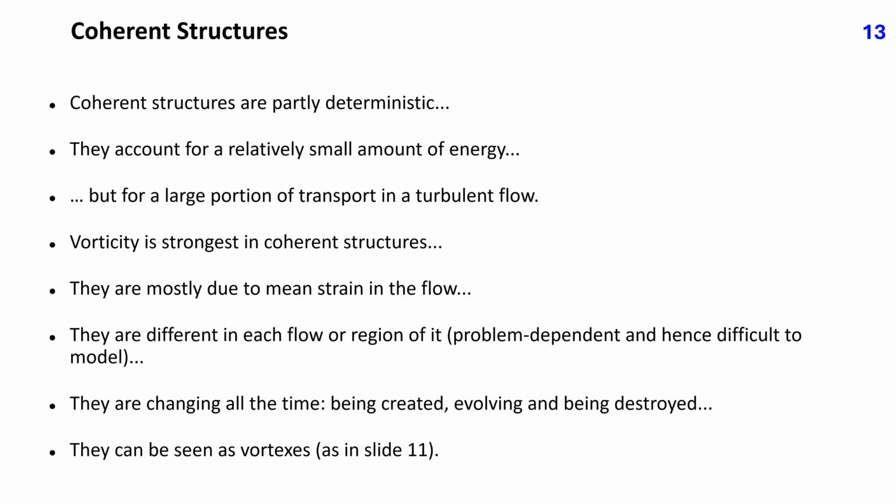Coherent structures are partly deterministic. They account for a relatively small amount of energy in the flow, but they are usually responsible for a large portion of transport in turbulent flow. Coherent structures are characterized by strong vorticity. They are mostly due to mean strain in the flow.